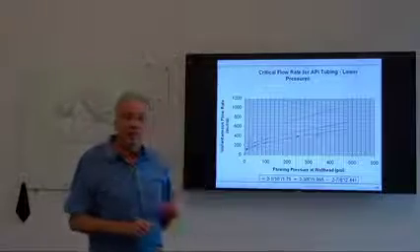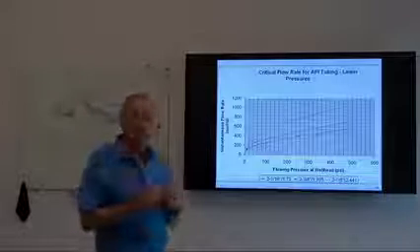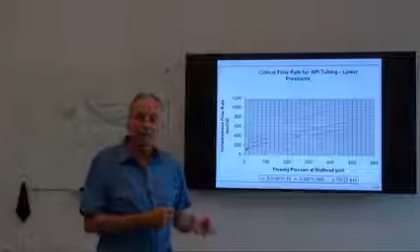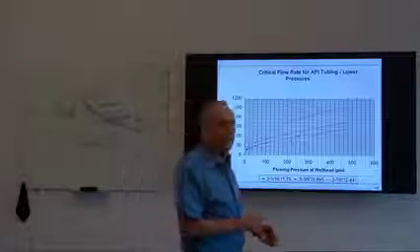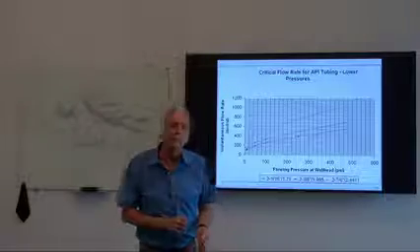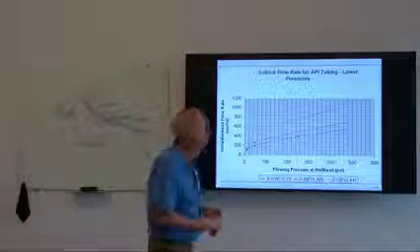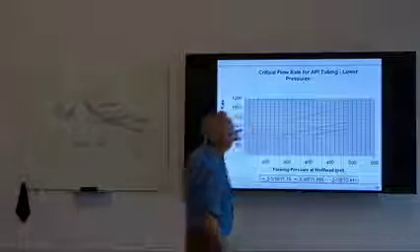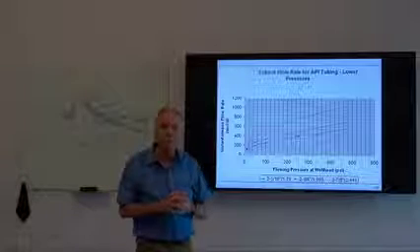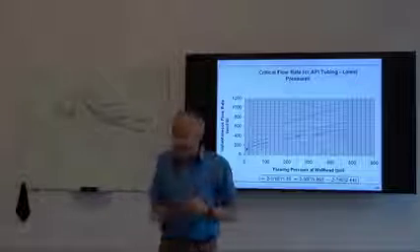So that is telling us that our bottom hole critical rate, the point at which, in a vertical well, it would take to suspend droplets at the bottom of the well, is 700 MCF a day. Yet it's only 550 MCF a day at surface, where our flowing wellhead pressure is 300.